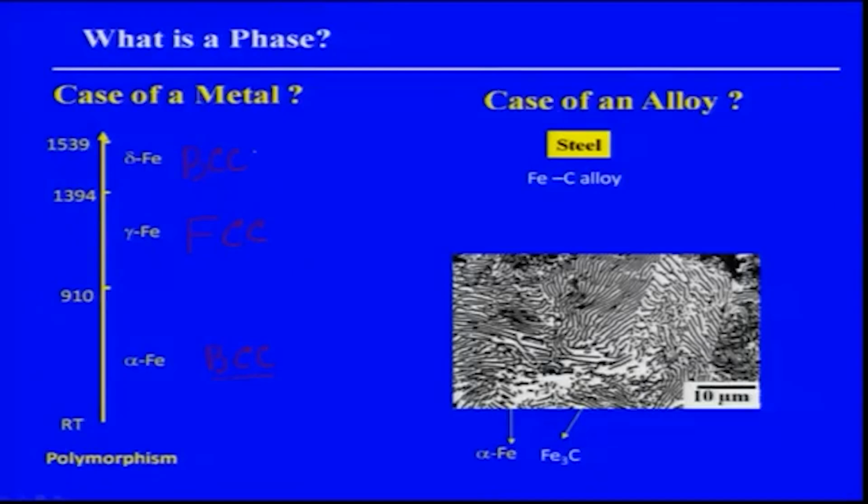But what happens in the case of alloy? So, pure iron is still understandable. Remember, beta iron is nothing but a high pressure phase which is not shown in the 1 atmospheric pressure system, that is normal STP. We never show beta iron, but beta is sometimes called beta, sometimes called epsilon iron, but it is a high pressure phase. That is why beta is omitted here.